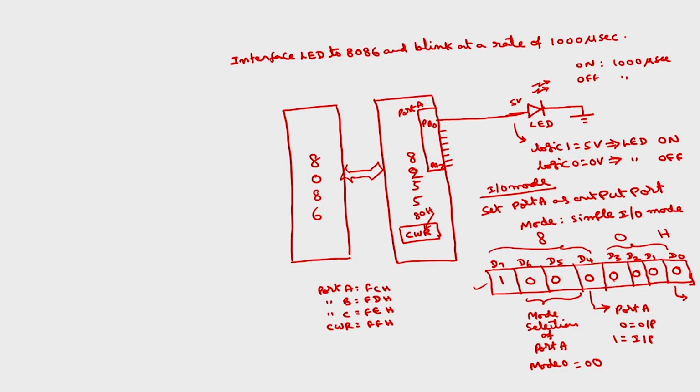Okay. So, in order to write the program, I have discussed 2 instructions called in and out instructions. These in and out instructions are used for reading and writing data from the ports. First of all, you take move data segment register with some address, the same as the other instructions that I have written, move DS, AX.